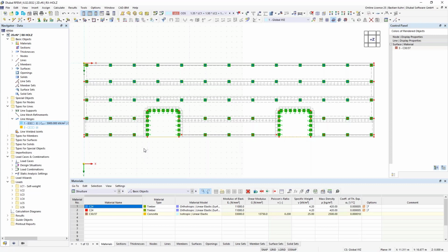I'm using the control function for this because it's quite a nice function. If you are coming from RFEM 5, this process, what I'm doing right now, would not really work in RFEM 5, because now I can only activate additional objects and still keep the surfaces selected. So this one I missed here. This one we need, this, and this. Okay, that I did not grab, but everything else I have.